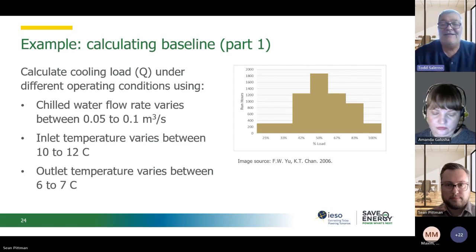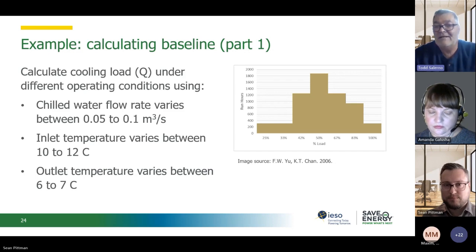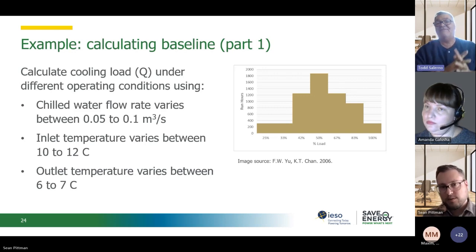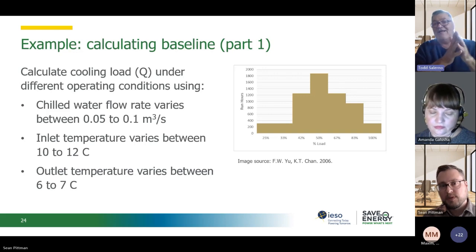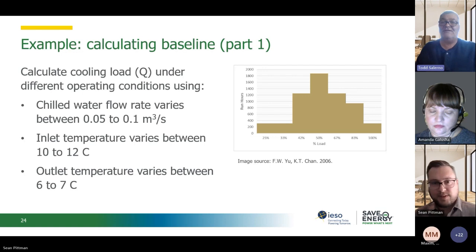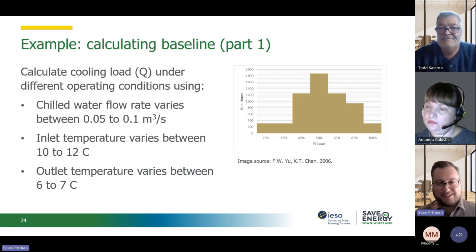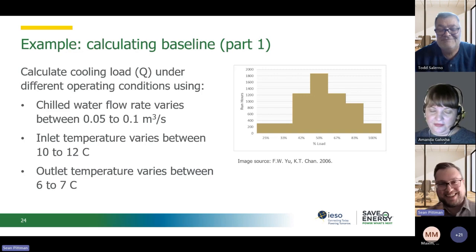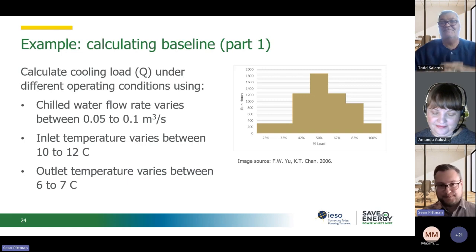Then if you get into some situations, especially like I found with commercial refrigeration, like cold storage and food processing, that can be a little more difficult because you're starting to get into batch processing. So you might have to get it narrowed down to what a particular batch uses and then project that over the course of a year. Yeah, it's definitely one of those things you can get down the rabbit hole on pretty quickly on trying to find those multiple different approaches for different production processes.